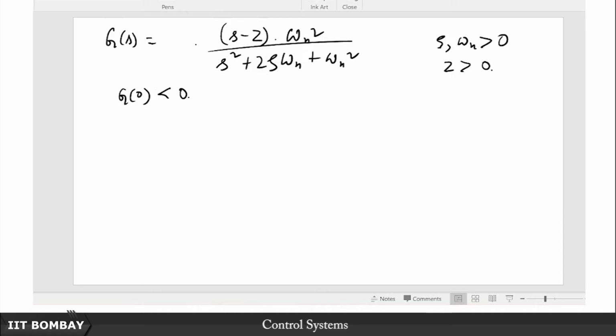So in other words, if you try to find out the step response of this system, you will see that if you apply a unit step like this as an input, your output in the open loop would behave in a weird fashion. It would behave something like this and would finally probably settle down to some negative value. This is going to be your steady state value. So this is going to be your output. Now clearly, as I just illustrated with that example, this is not something that conventional systems desire.